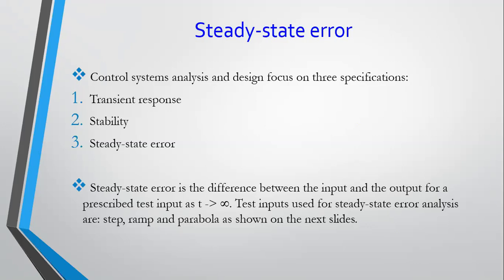For transient response, in that chapter we saw topics like percentage overshoot with things like damping ratio, natural frequency, settling time, and rise time for second order systems. We've done that for first order systems as well, but the chapter on second order systems is more relevant to us because it covers a broader type of response we can get from systems. We're going to see later how to approximate high order systems to second order systems.